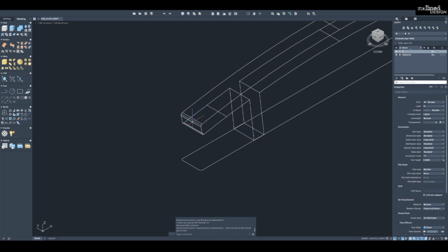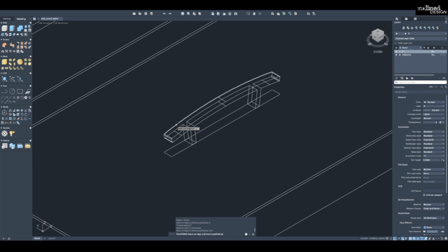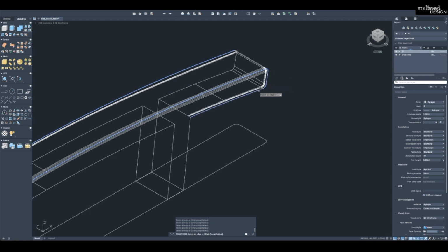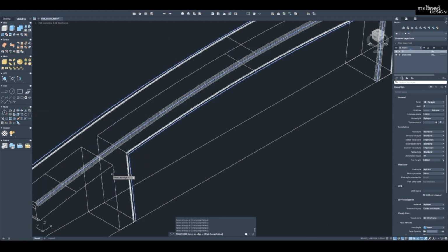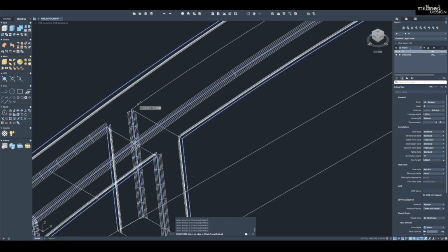You can see that this component already is radiused on the edge, but we can do the rest of the radius now, and then we'll copy it. So we're going to fillet the edge. We're going to enter distance 1/32, and then we're just going to select outside lines. You have to select the corner line, and you can select all of these, and we'll go right around the component. And you'll see that it's turning all the lines that we selected blue so that we know which ones are included. And again, working in wireframe kind of allows us to see all of these lines that we're selecting.